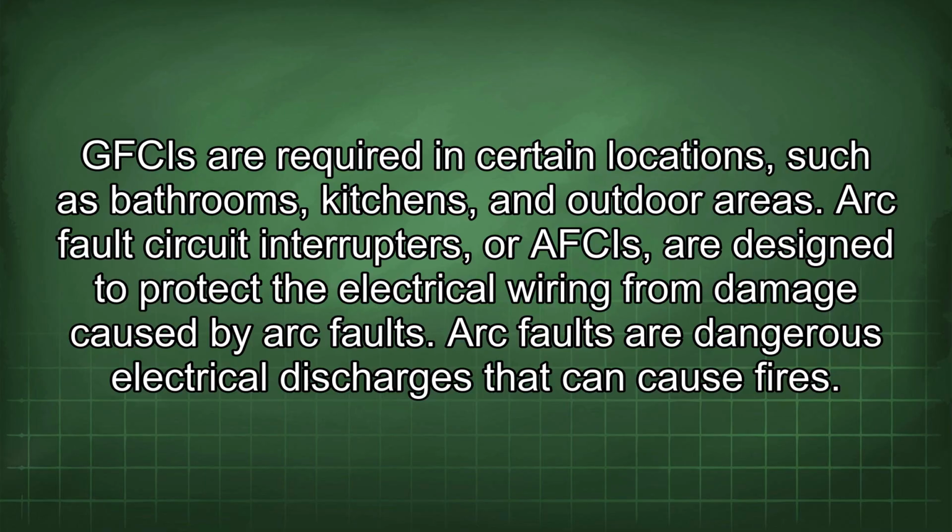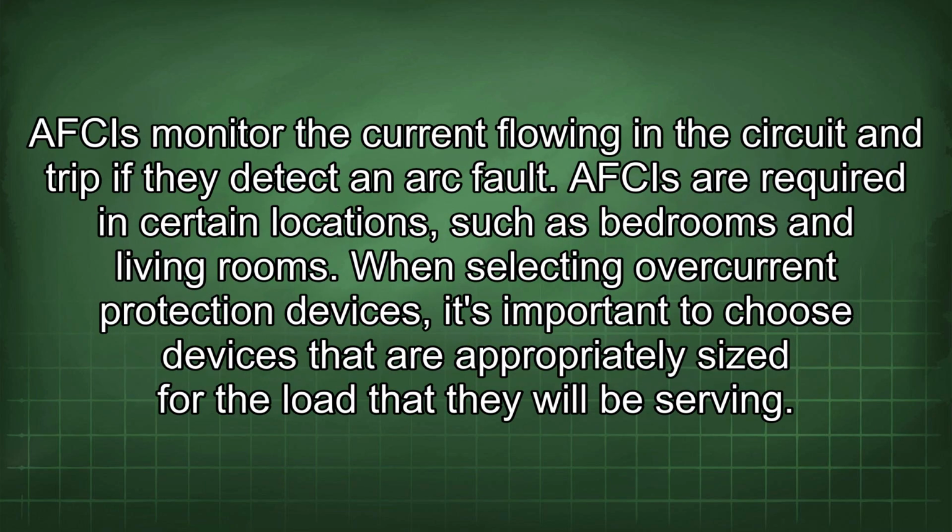Arc fault circuit interrupters, or AFCIs, are designed to protect the electrical wiring from damage caused by arc faults. Arc faults are dangerous electrical discharges that can cause fires. AFCIs monitor the current flowing in the circuit and trip if they detect an arc fault. AFCIs are required in certain locations, such as bedrooms and living rooms.